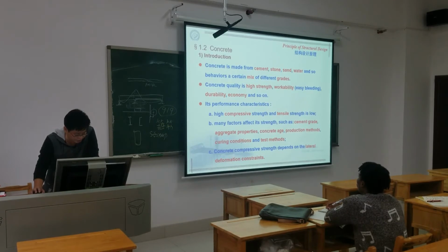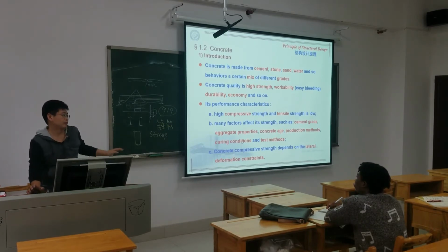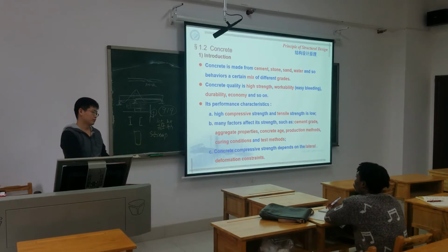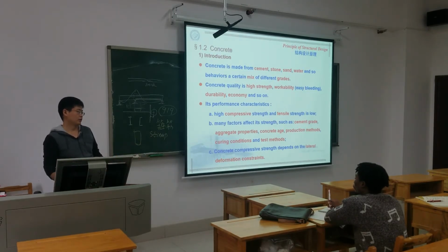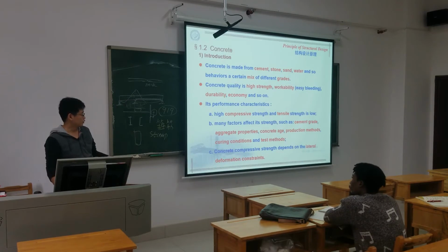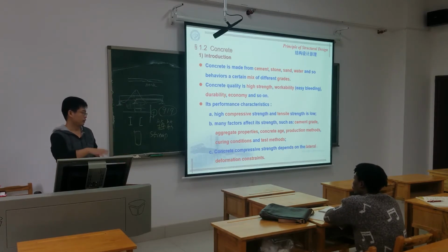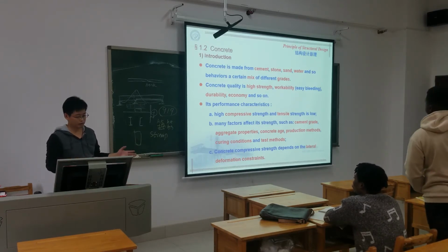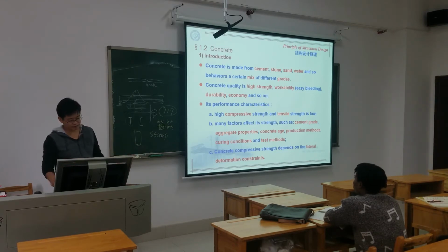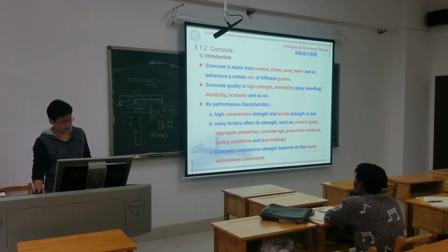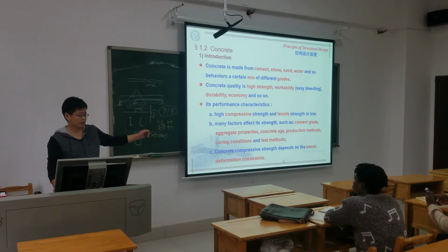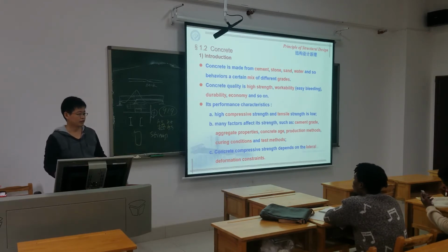Next is the curing condition. We all know that after we put the concrete into the mold, we need to cover it or use some water to make it wet, to keep it in good condition while it dries. If you just leave it there, maybe in the end there will be some cracks and the strength will be low.